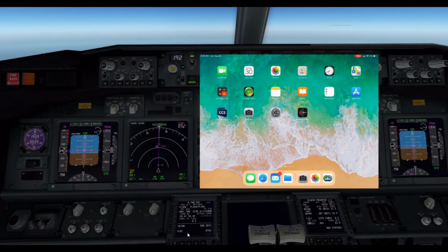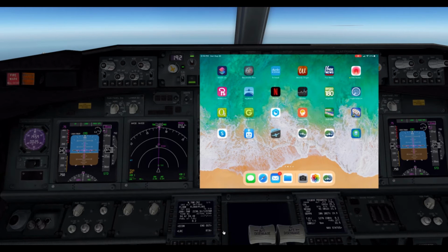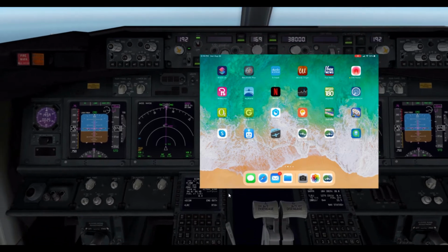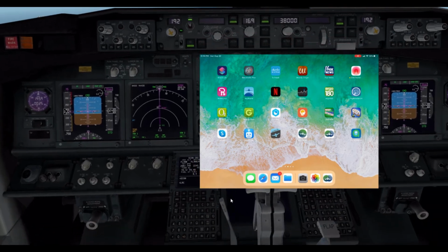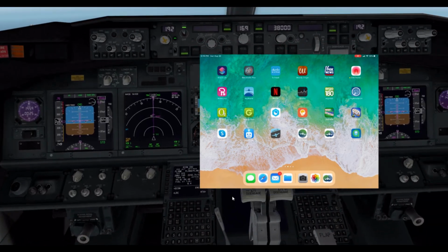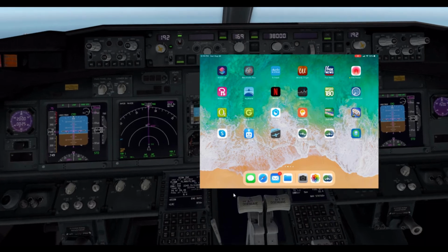Well, we are still in the climb and beginning to coast out. Let's open Ergo360 and see how the app is used in normal conditions. Flight plan information is automatically uploaded into Ergo360 in the ADS Oxygen ETP from a single source document. This should be accomplished on the ground using cellular or Wi-Fi, but can also be accomplished airborne if these services are available. This data automatically fills in all entries needed to drive both programs.